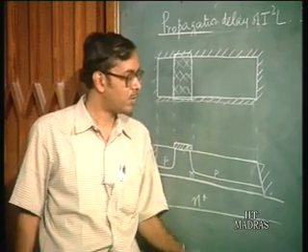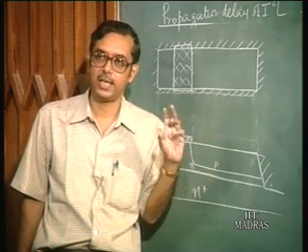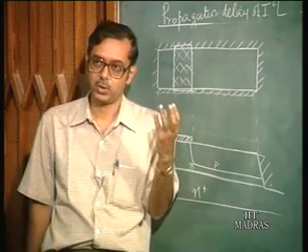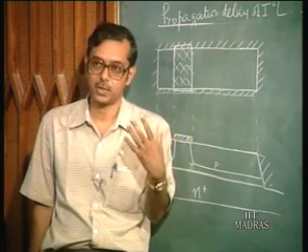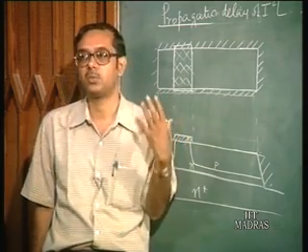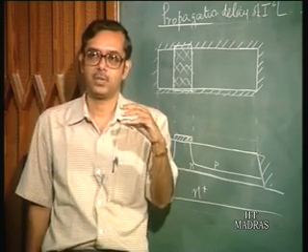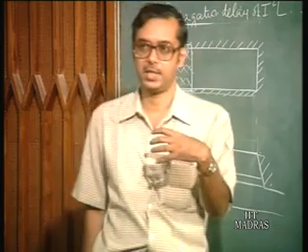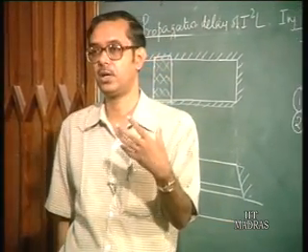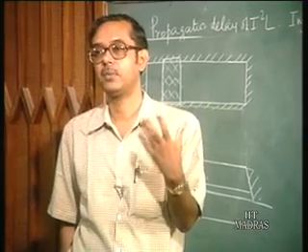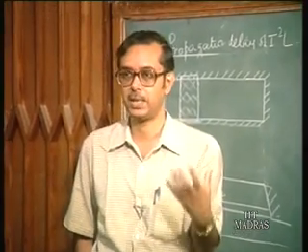You can deposit polysilicon, and the advantage is that you can dope it just like silicon, and if it is very heavily doped with impurities, it behaves almost like a metal. You know that in silicon, if the doping concentration is high, the resistivity is low. So if you make the impurity concentration very high, the resistance becomes very low, and it behaves almost like a metal.